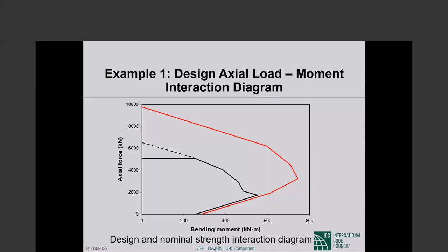You already discussed this. That's what I was saying. Every other bar has to be laterally supported, and if you have more than 6-inch clear spacing, then additional lateral support may be needed.